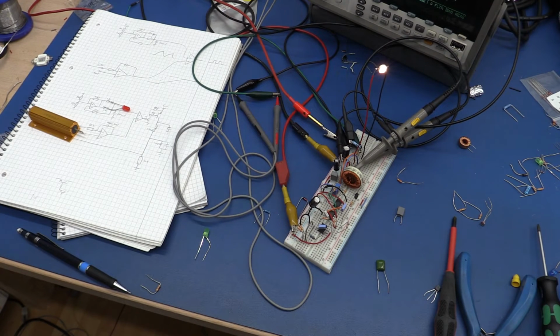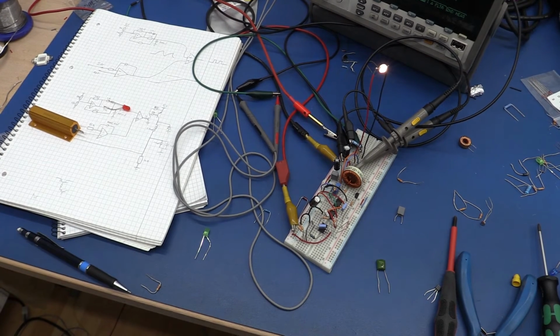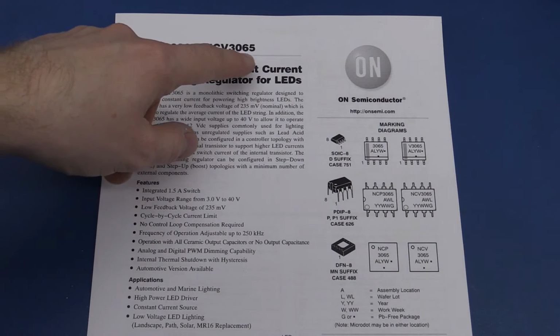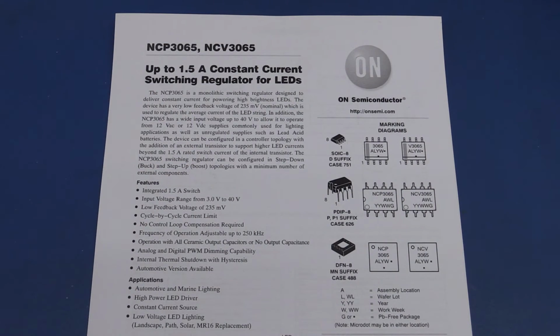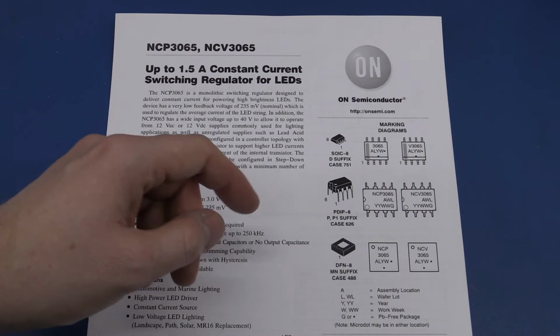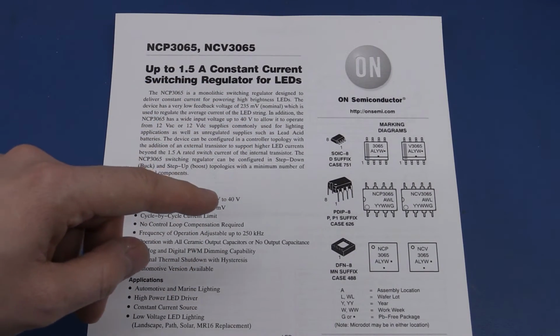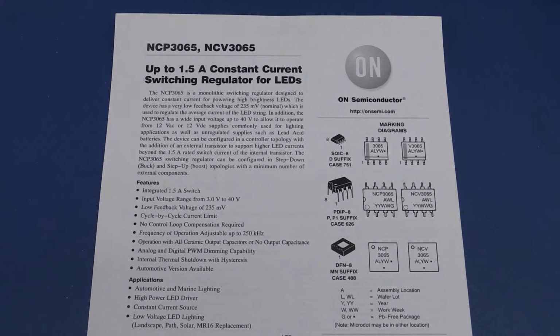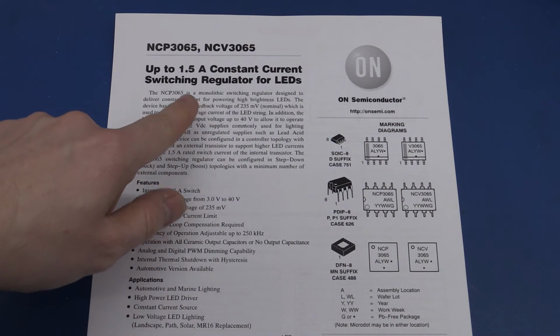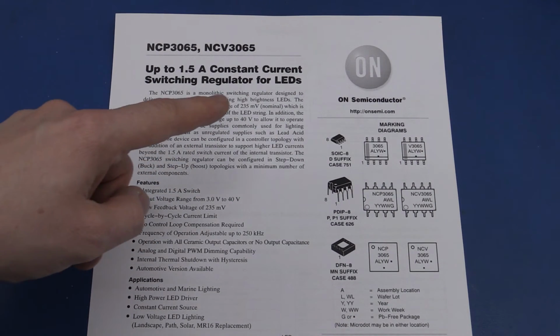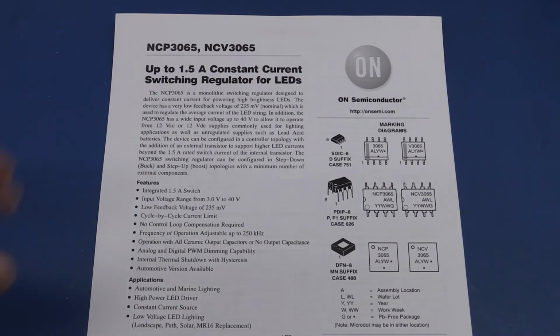Perhaps we should look at a bought one that has a much greater efficiency. So the chip that I chose is the NCV3065. The reason why my choice fell on this chip was mainly the price. It's around $1.5 a piece for one-off quantity. It goes up to 1.5 amps, and it's a constant current switching regulator for LEDs. That's really all I had time to read